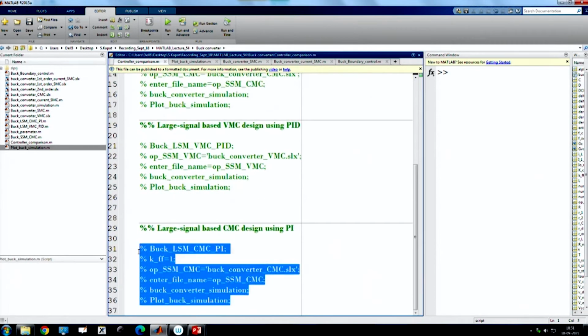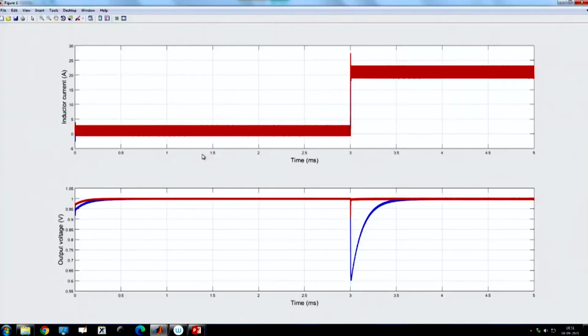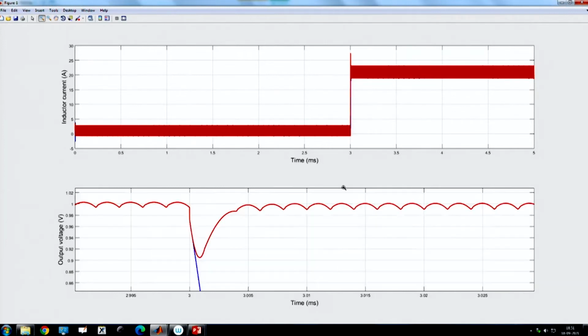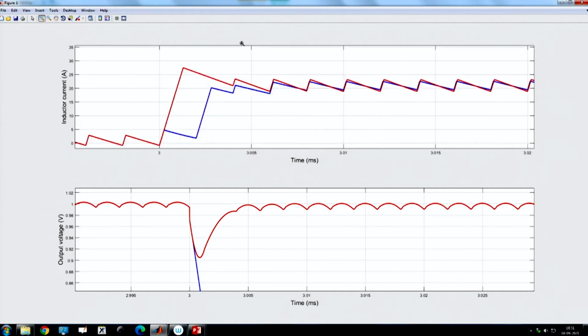and we want to enable this large signal based tuning. So, you will find, because large signal based tuning almost achieves very fast transient response, almost close to the optimal condition in one switching action, more or less. Okay. So, you can achieve very fast transient response.